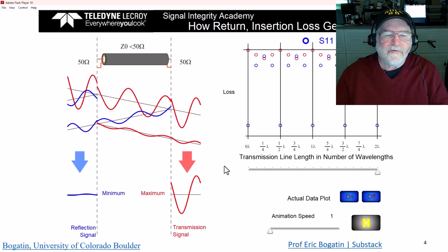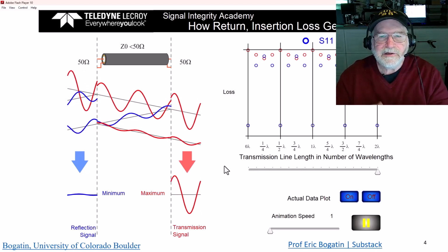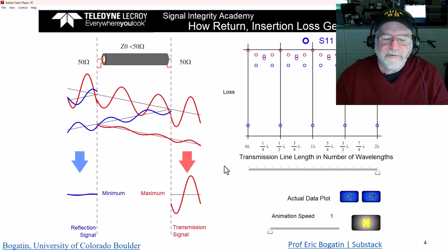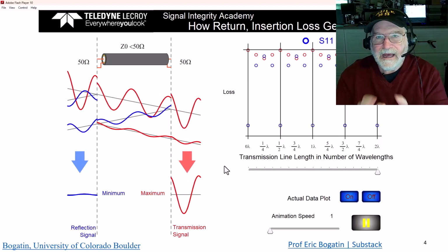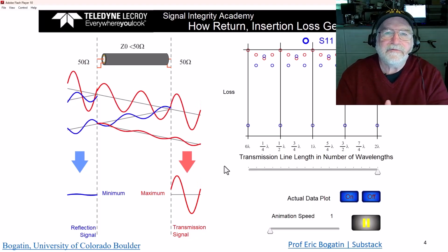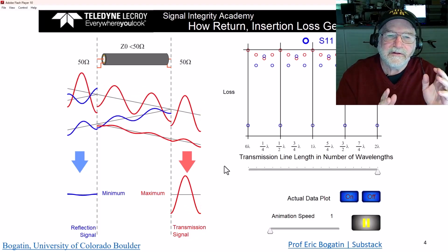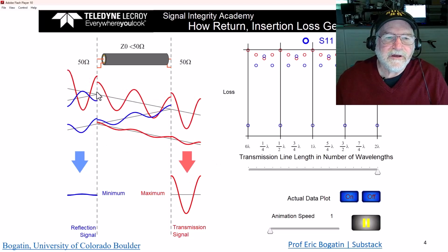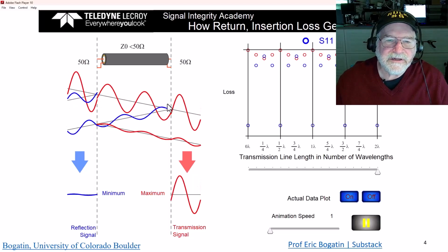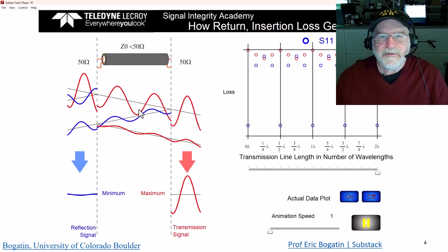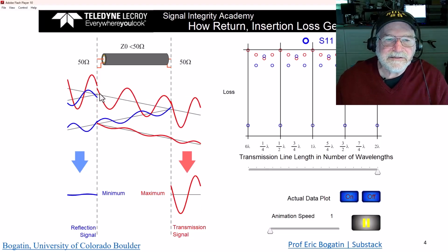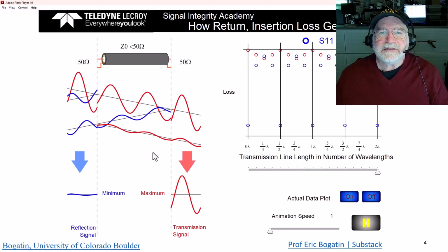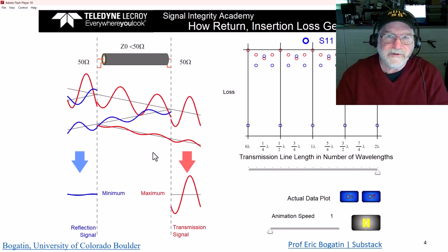I find this, again, a very useful tool. You're not going to necessarily learn from scratch how the waves reflect, but if you apply rule number 9 and you come in having an understanding of how S11 is related to the reflections from the first interface and the second interface and the multiple reflections, this illustrates those very clearly and helps to cement that understanding. And that's really the purpose of all 4 of these tools.